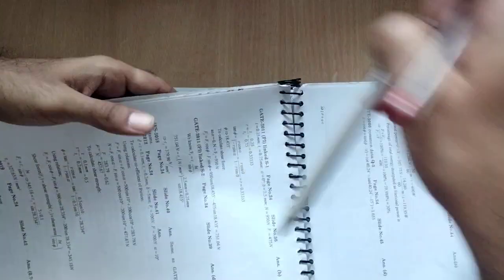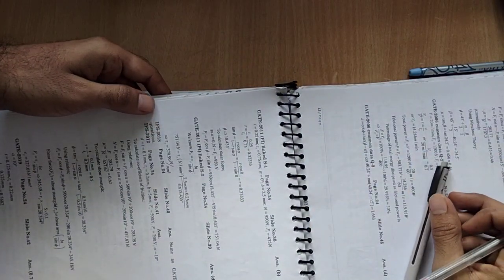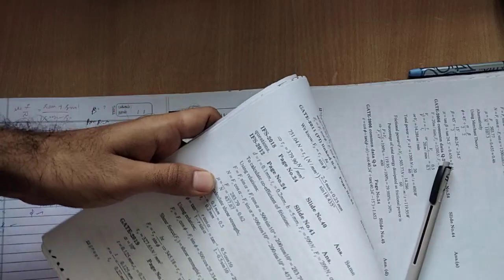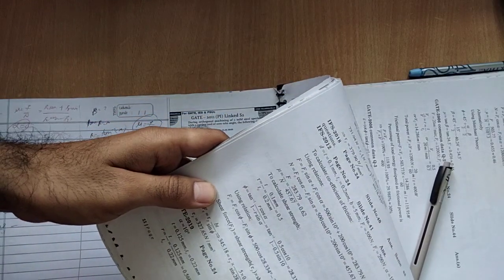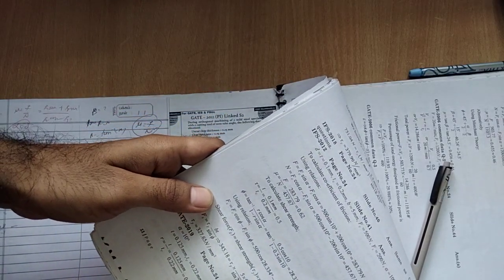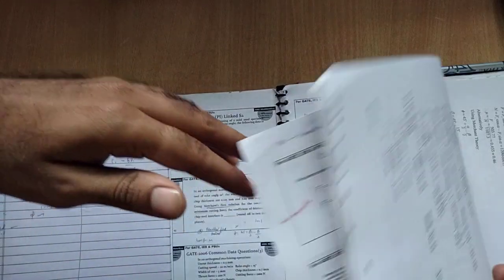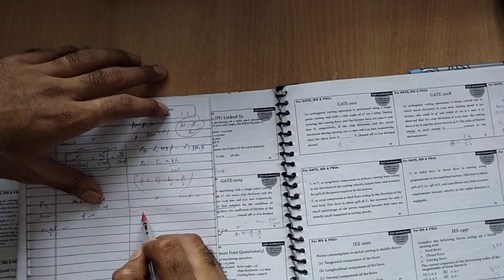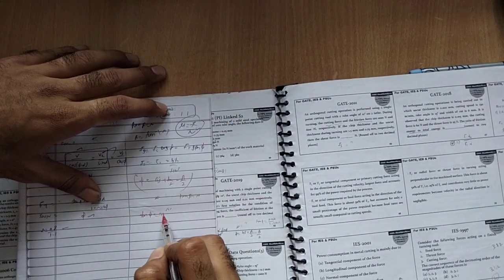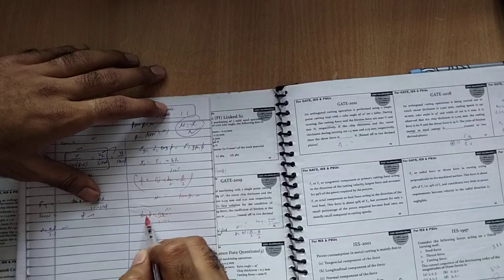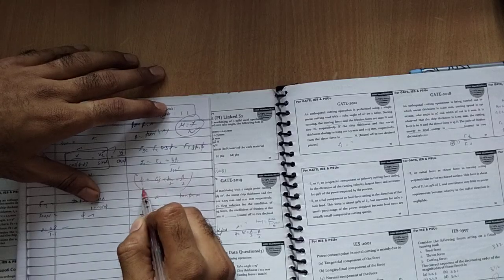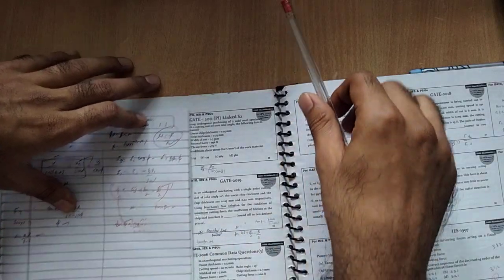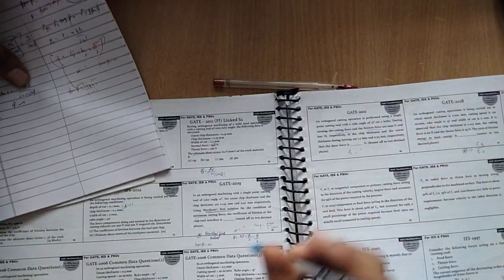Or calculate, yes, as I just told before. So you can see tan theta equal to r cos alpha divided by 1 minus r sine alpha. So calculate theta, it means shear angle, put the shear angle here and calculate the beta. That's it. So just a simple question, you can just do it.